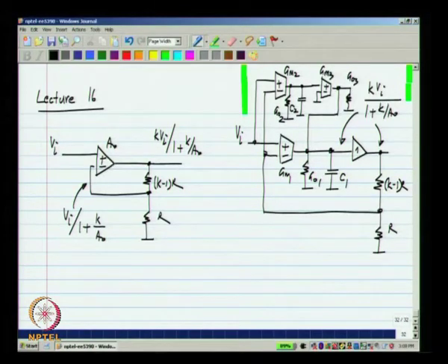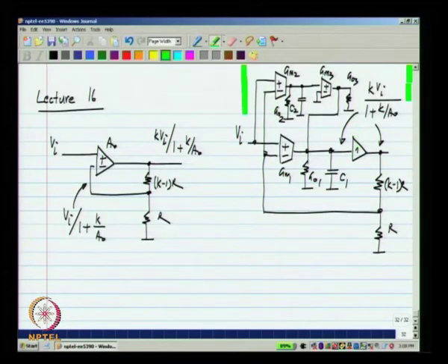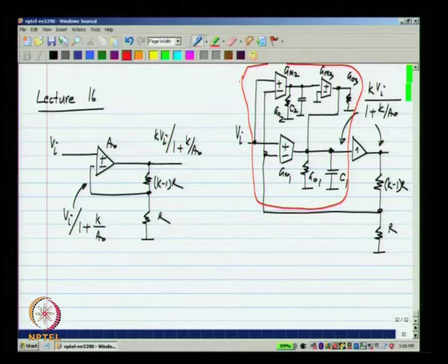Okay. So, it is one thing to get an idea, and the next thing is to put down all the non-ideal effects that come in while implementing the idea and see if it really works. So, now I can call this entire complicated beast my op amp. Because whenever I make an op amp negative feedback circuit, I am going to use the whole thing. This was my original op amp, but to fix the steady state error of this I need all of this stuff. So, I am going to use the whole thing, and that is my new op amp. I may or may not use the buffer as usual.